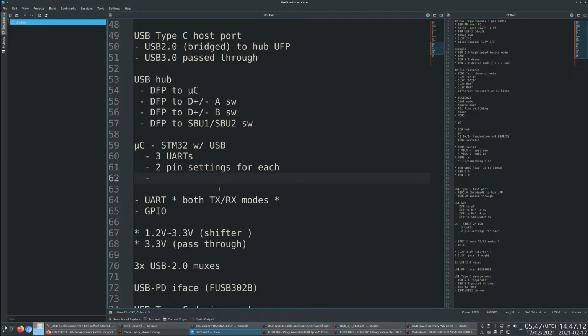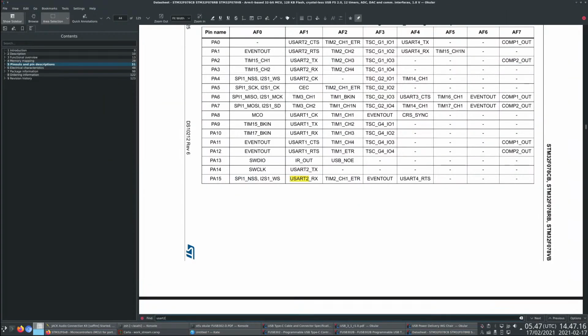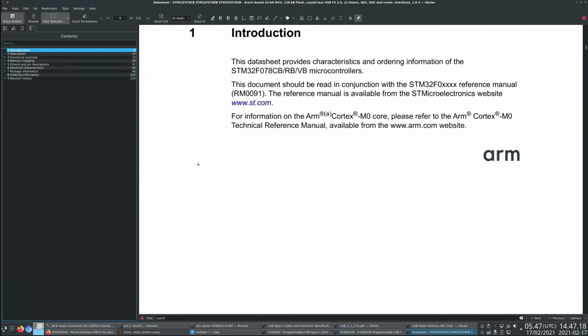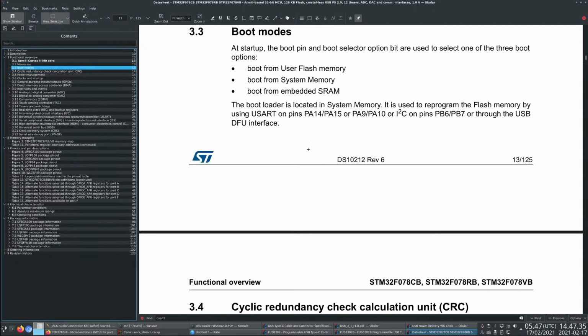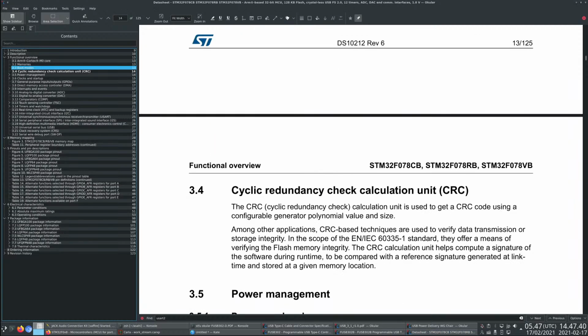Yes, I want to configure factory programming of the STM over the USB-C cable. The idea is that these things have bootloaders that can do DFU, so I want this to be unbrickable, basically. From the point of view of the host, it's going to be a dumb USB 2.0 device behind a hub when you boot it up. If I remember correctly, there should be a boot option.